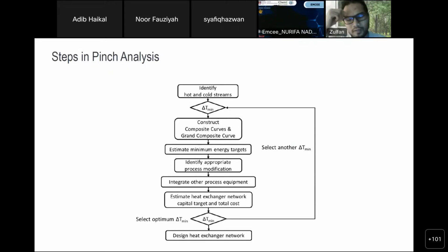You have your plant data, and from this plant data, you calculate the mass and energy balance. It may or may not be complete, but you have to do it. And that's why we need to have engineering judgment and knowledge of your process engineering. And once we have the data complete and it makes sense, in completing the data, we could also use process simulation to simulate the whole plant, the scope that we are going to do.